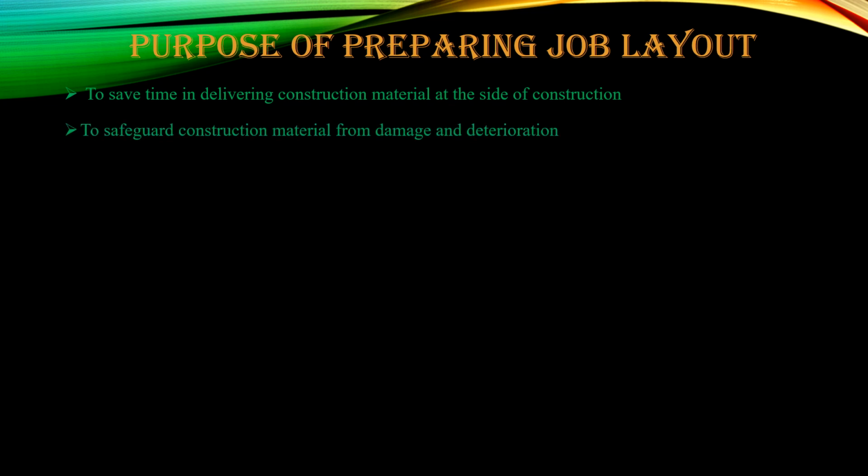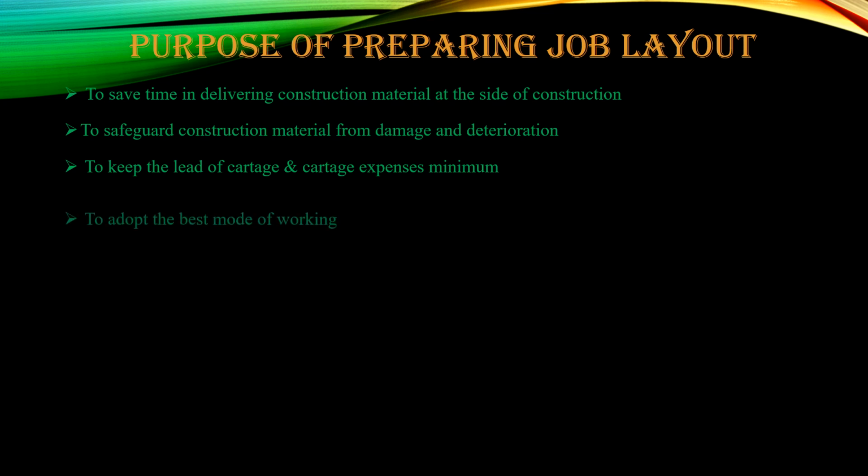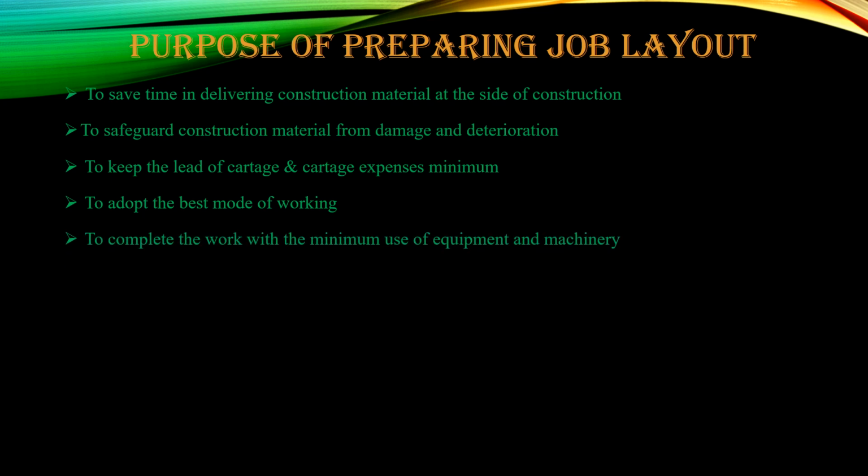Next is the purpose of preparing job layout. In order to save time in delivering the construction material at the site of construction, a job layout is necessary. To safeguard the construction material from damage and deterioration, to keep the lead of cartage and cartage expenses to a minimum range, to adopt the best mode of working, to complete the work with the minimum use of equipment and machinery,